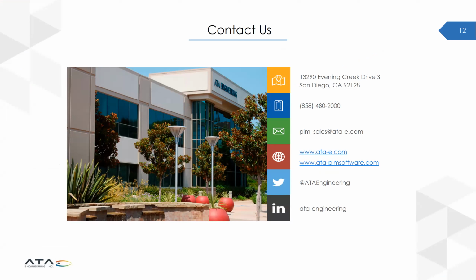I guess, Laura, a quick question while we're waiting for any additional ones to come in. I know you said not covering layers, but any initial thoughts or big differences between groups and layers? I personally find groups a lot easier to work with than layers in Femap. I find it a little bit easier to pair with Nastran, and especially, as I was mentioning, if you've got a large model with lots of parts, groups are going to be really useful to view your model that way. Layers has some of its own quirks, and I just personally don't tend to use them. Agreed. I'm also a group man myself.